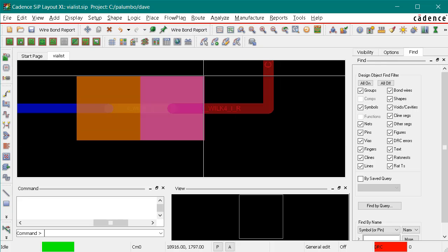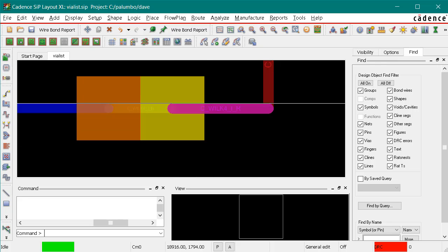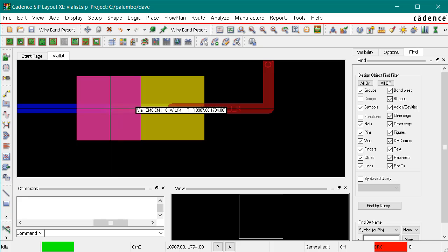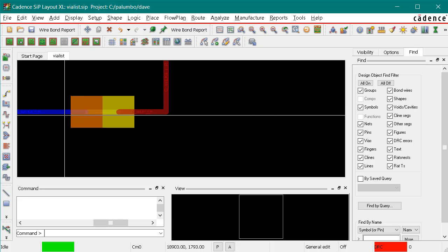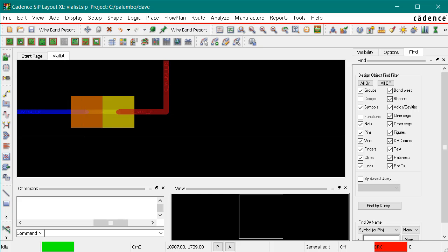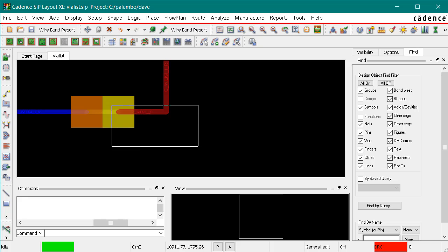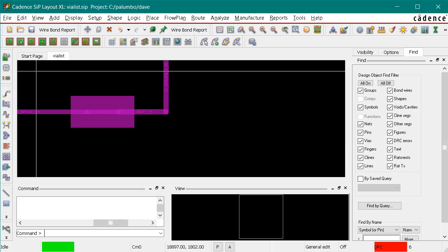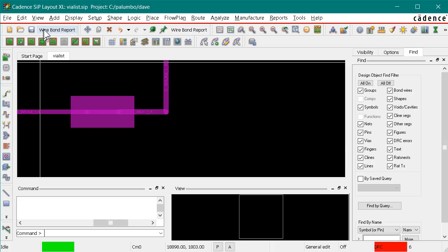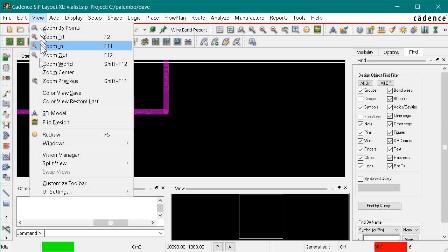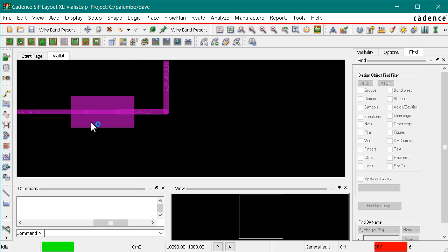Similarly, when we wanted to go back, it dropped a via from CM2 to CM1, staggered the exact distance we wanted, and dropped a second via from CM1 down to CM0. And just to super verify that we got what we wanted, we'll select these elements again and select View 3D Model.